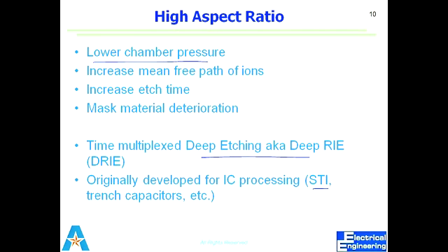You know that by increasing the pressure, your etch rate increases. But in the background, by increasing the pressure, you are supplying more etchant species. It means that the mean free path may be affected, so there is a trade-off, it will be decreasing. These are just to give you an understanding of why the increase or decrease of pressure affects my etch rate. But while working on the equipment, you don't need to worry about the mean free path of the etching species, so you don't go into that much detail. This is just for discussion purposes.